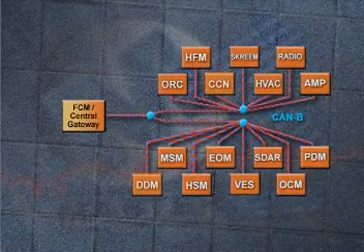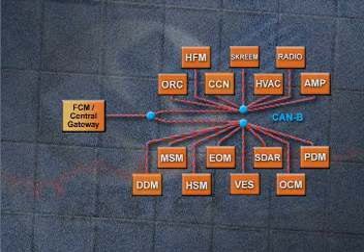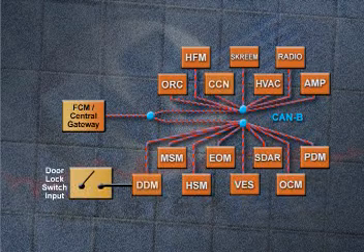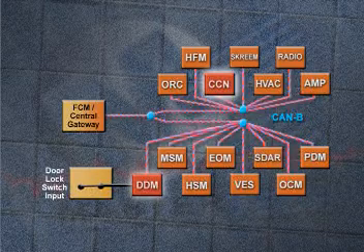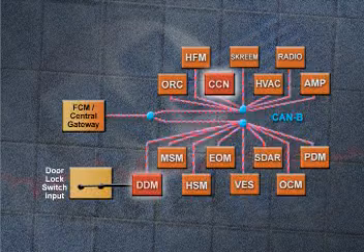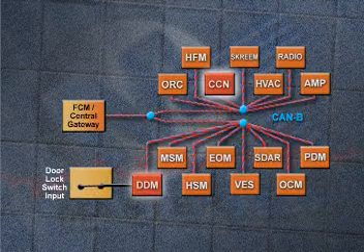Design features like arbitration are not something you're going to notice in CAN bus operation. One big difference you will notice is the way in which modules and their inputs and outputs interact. A lot more of that interaction depends on the bus network now. That's because the inputs and outputs needed for any particular system can be hardwired to modules based on proximity or convenience. This is different from systems in which inputs and outputs are always wired to the modules which use them.